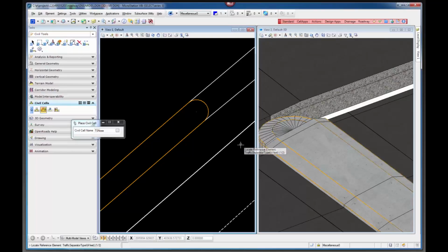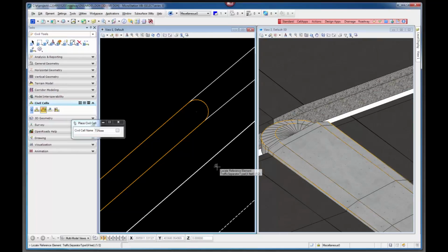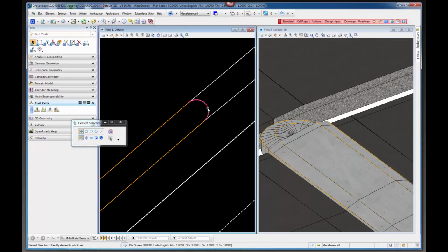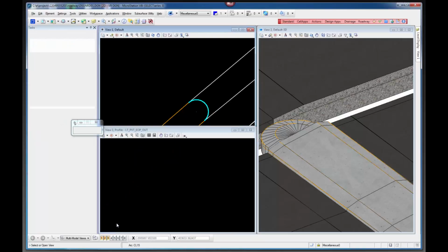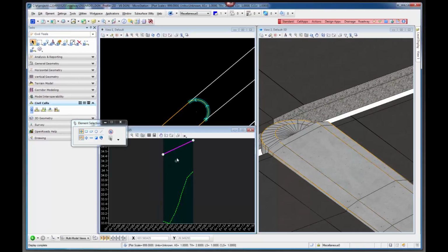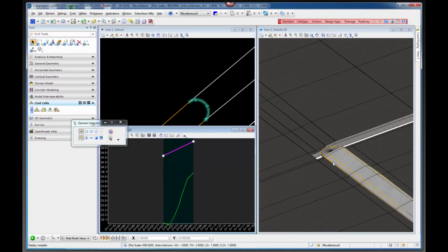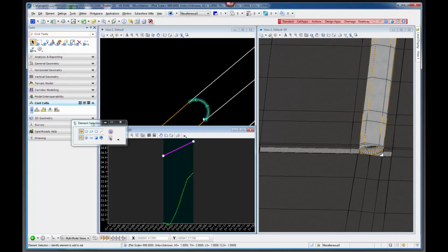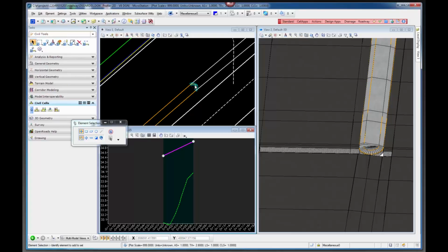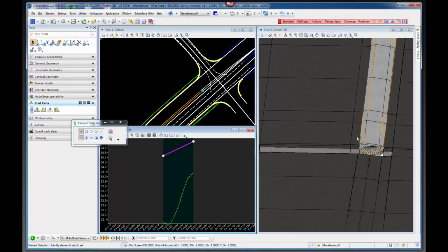Now sometimes the profile, it doesn't catch the profile, but you can simply edit it by clicking on here and going to the profile view. And if you click in this view, you see this is the profile that it was trying to get from those 2 points. And if you need to adjust it, you see the direction of the nose. It looks like it's going from the left turn side, which would be this side, to around to that side.